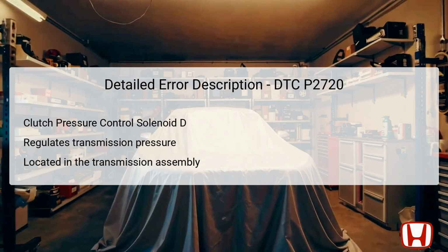It's essential to note that the function of the solenoid is electrical. Thus, mechanical problems within the transmission typically do not cause DTC P2720. A careful inspection of the solenoid and its electrical connections is necessary to pinpoint the specific cause of the low input signal indicated by this code.